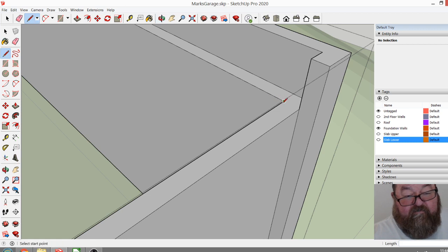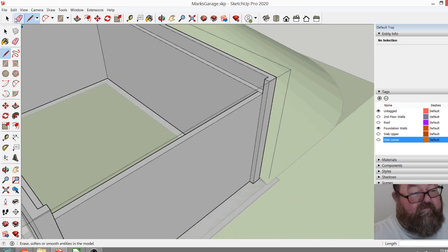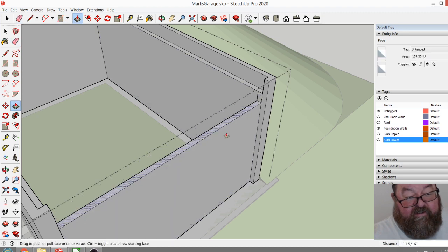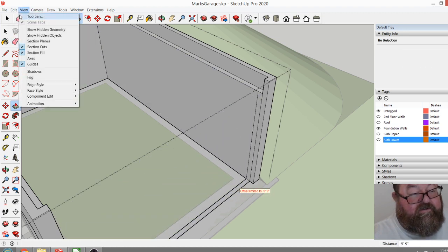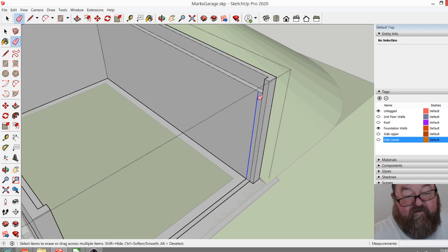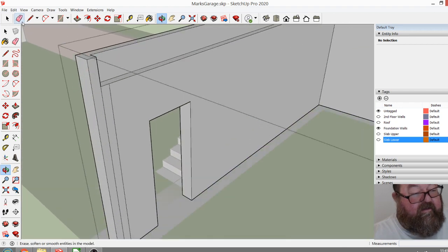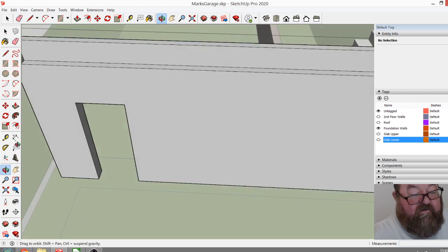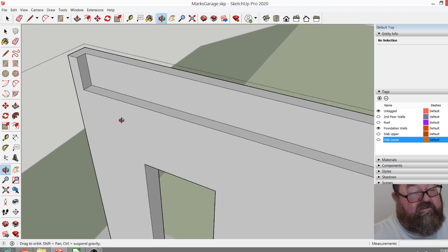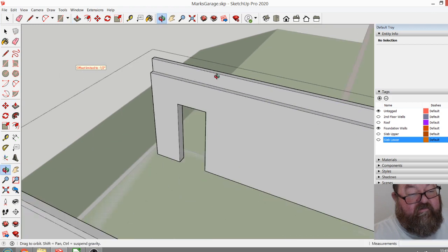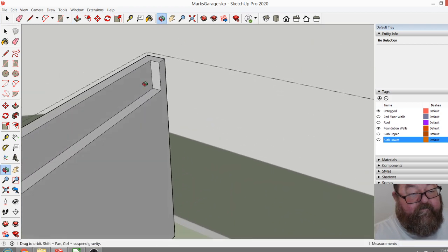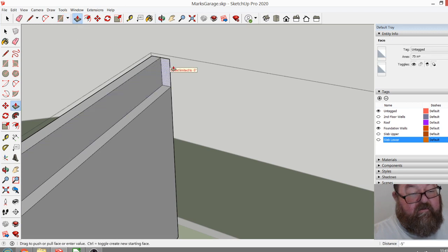But it is helpful if you go into some amount of detail in this construction or schematic design phase, because if you do go forward, you're very much prepared for what you'll run into. And now I am realizing that this notch will need to go all the way back because of our steel beam. If you want that open back there, you would have an additional steel beam.